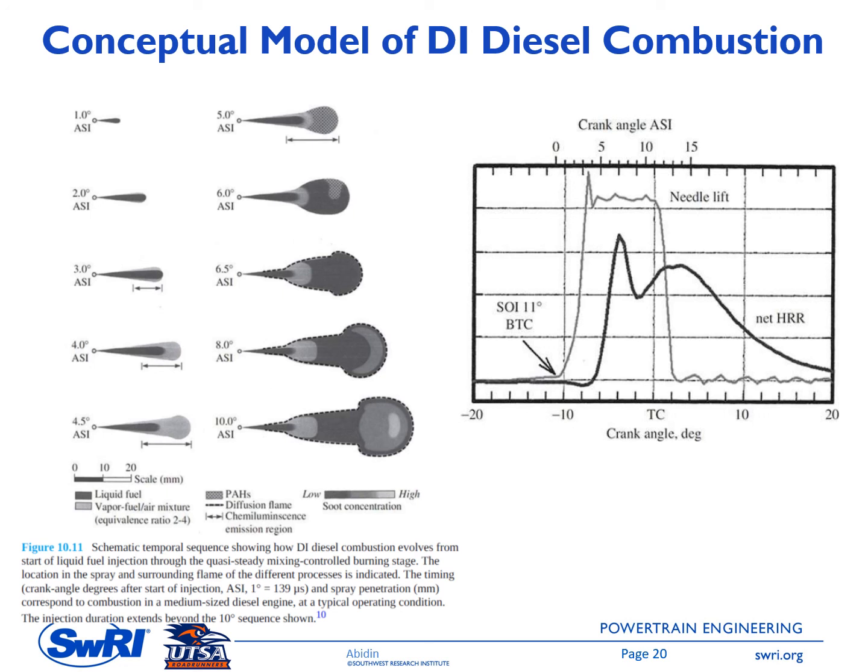and the dotted points here represent the premix flame. The first picture shows the spray at 1 degree after the start of injection. ASI here stands for after start of injection. At 1 degree after the start of injection, the fuel is mainly still in liquid form, so this dark color, and this is at 2 degrees, and then at 3 degrees after the start of injection, the liquid that was injected earlier has already evaporated. Some of it you can see as a light gray color there.